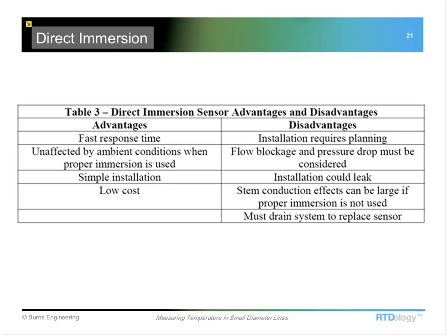Some of the disadvantages here: if you need to calibrate that sensor, you need to drain the system, and then you're going to be opening it up. In some pharmaceutical applications, that's not desirable. You want to be able to keep those systems closed so that they don't have to be re-cleaned if they are opened.